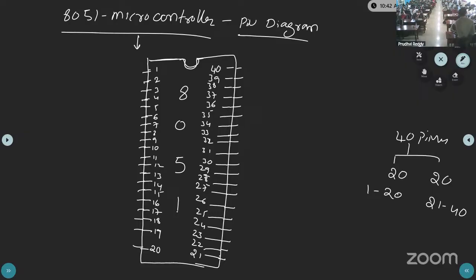If you take any integrated circuit, have you seen an IC physically? You can take any damaged mobile. To count the pin numbers there is a knob, a small circle or a shape symbol. From the left side of that, you can count the numbering for any integrated circuit, 1, 2, and so on, then 22 again bottom to top. Here on the left side it goes top to bottom, and on the right hand side bottom to top, in increasing order.